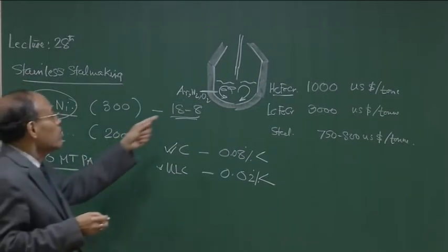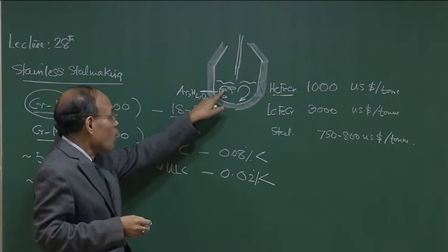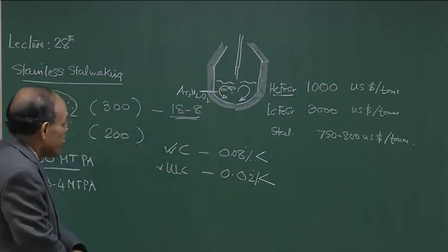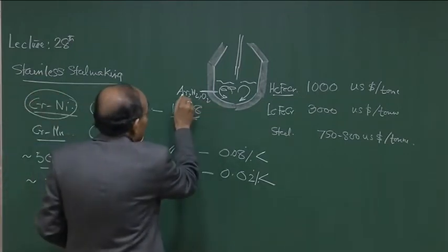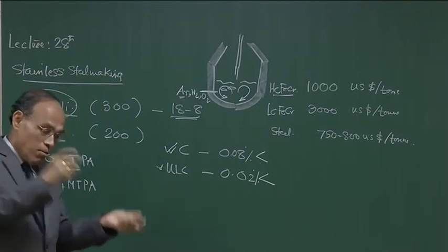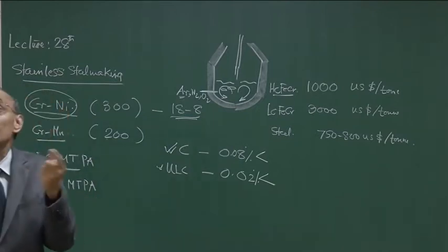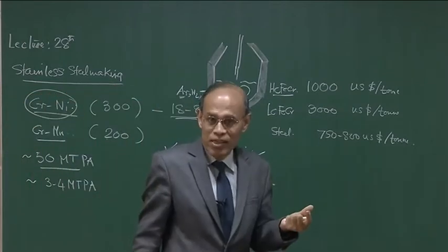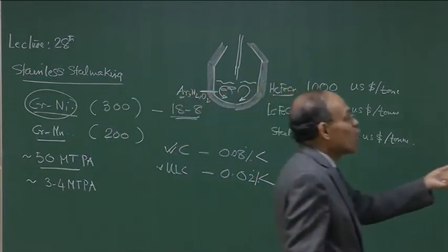The carbon monoxide bubble which forms at the melt gas interface will, in the presence of argon, give rise to a much lower pressure, as opposed to the case where we do not have any argon. So, this is called the dilution effect of CO in the system.